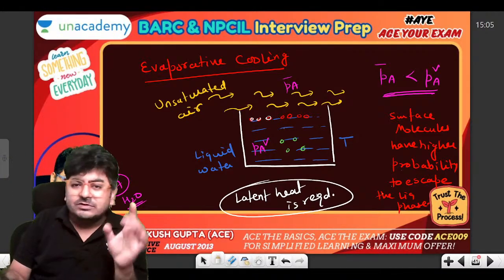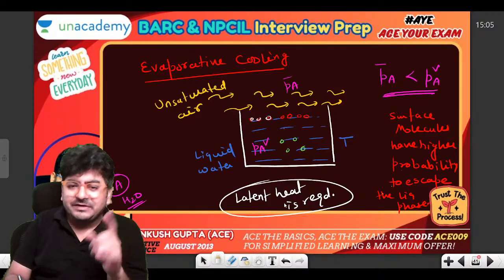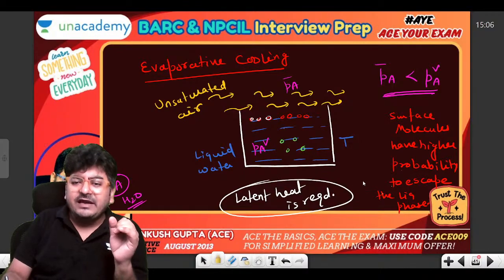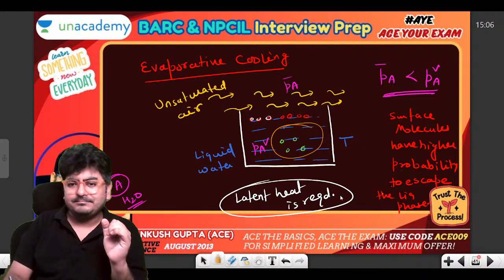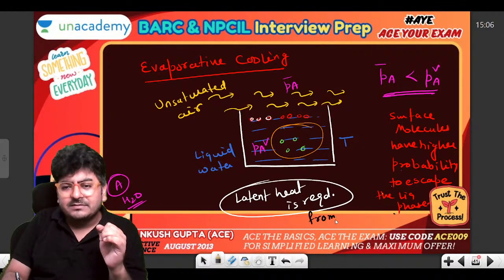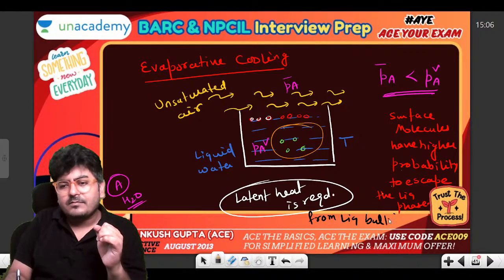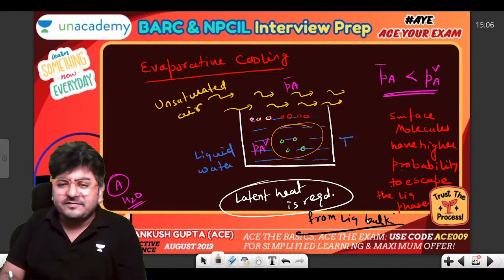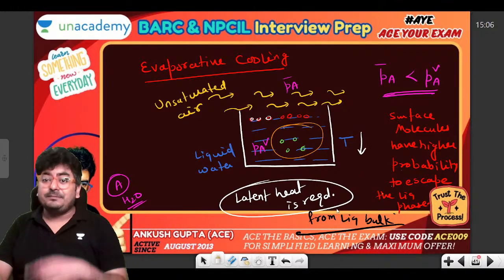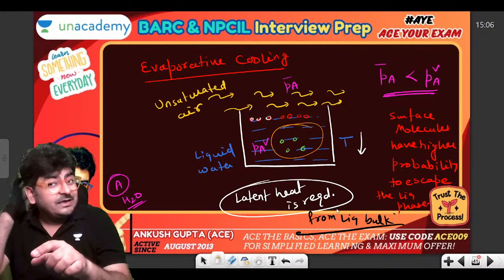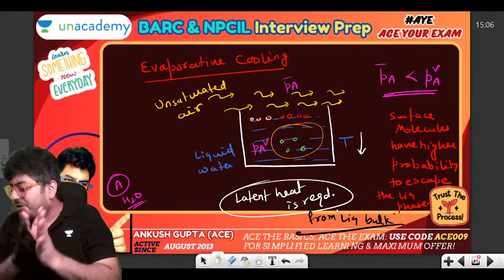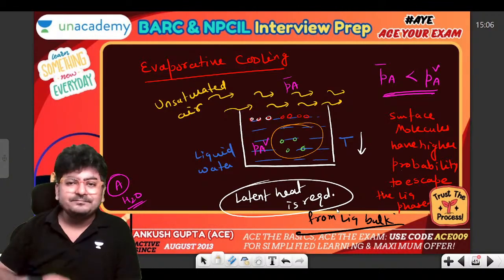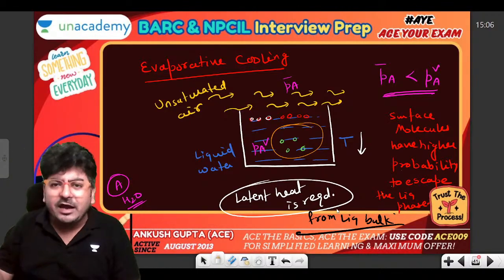No. So these molecules at the surface require the latent heat, and they will absorb it from the liquid bulk. Because of this, the temperature of the liquid decreases, meaning cooling occurs. Now you can see evaporation is taking place and cooling is taking place. This is evaporative cooling. That is the whole idea of evaporative cooling.